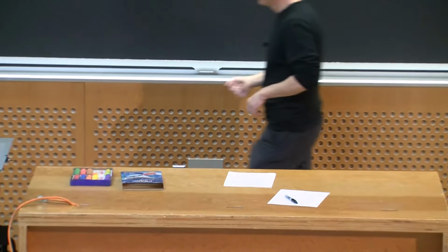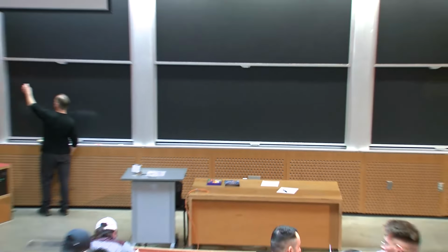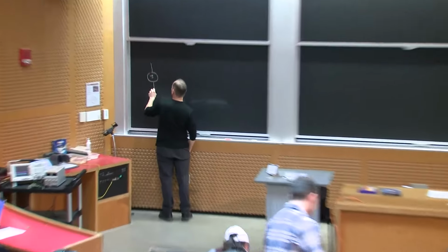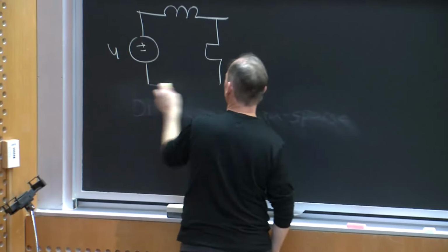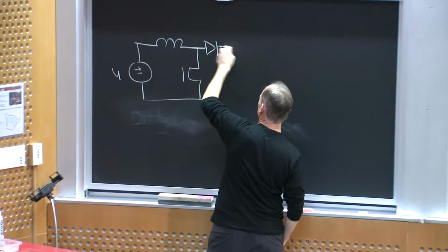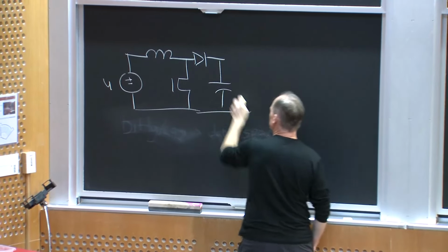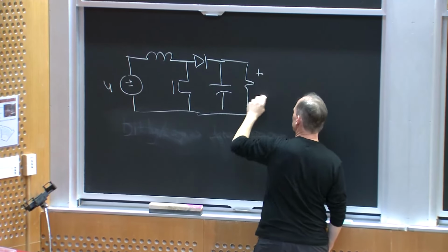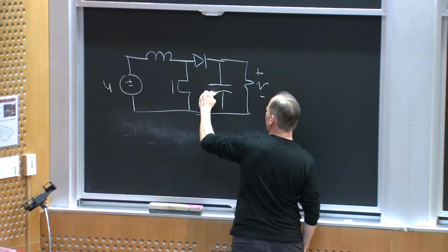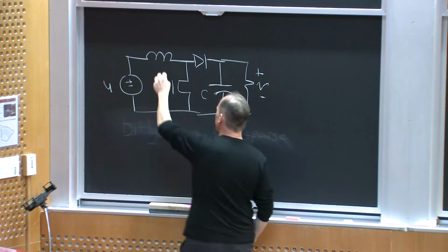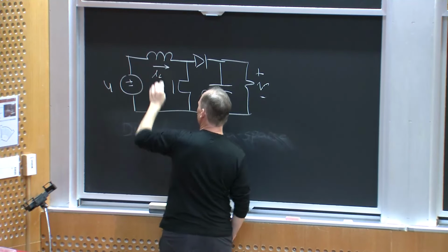Control, and we said that we saw a few phenomena. So if I took, for example, a boost converter as my canonical example, I have V, the output voltage, as one of my state variables because of the capacitor C, and IL is the other state variable.